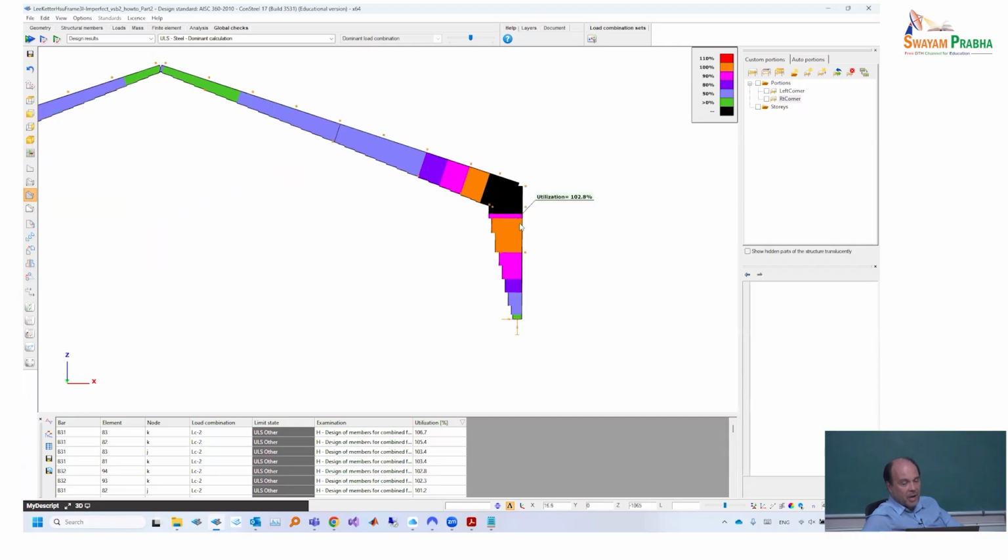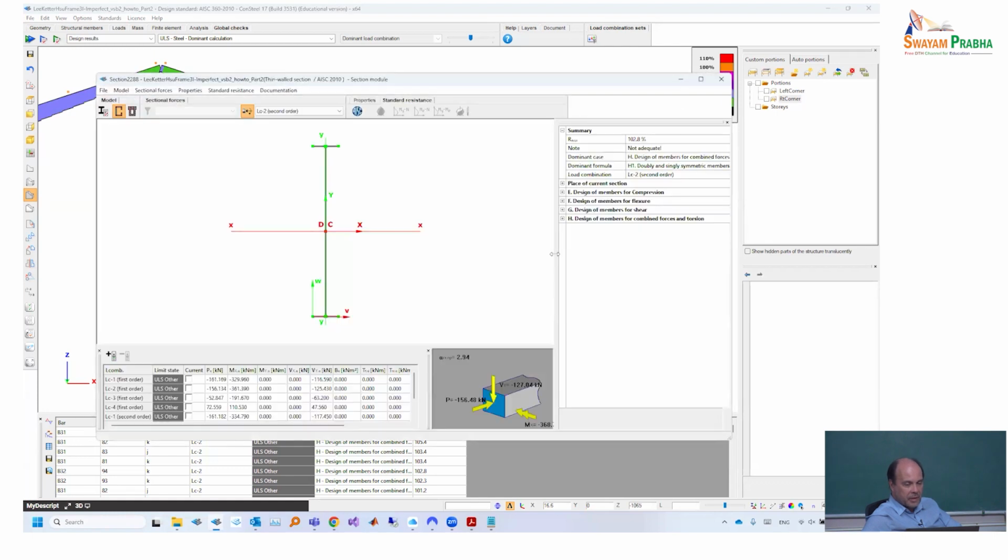If we come to the 102%, now if we check that connection, calculate connection, we see that it is still using the 2.94, which is probably, or we clearly saw, that that value is still the one which refers to the rafter and not to the column, so it probably makes no sense to use this value for the column.